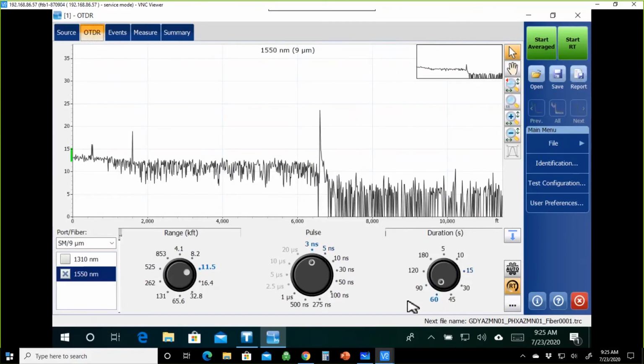the expense of time. Because the difference, for me in a maintenance situation, between 5 seconds and 90 seconds is not huge compared to the time I'll waste in fault isolation, trying to find something by driving around because I pinpointed the wrong place. So at 3 nanoseconds, I'm going to set this for 3 nanoseconds here. So it's going to be 3 nanoseconds at 90 seconds.